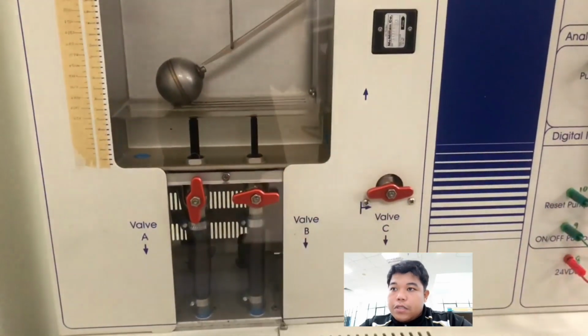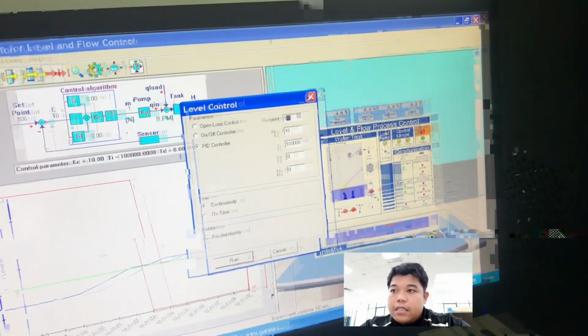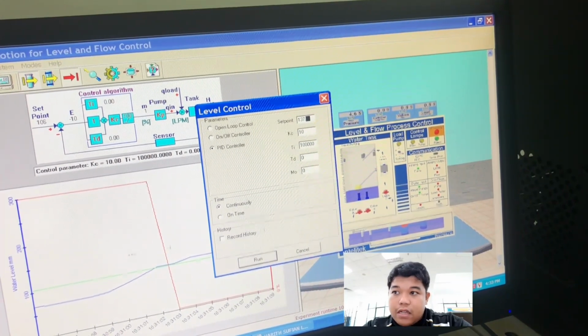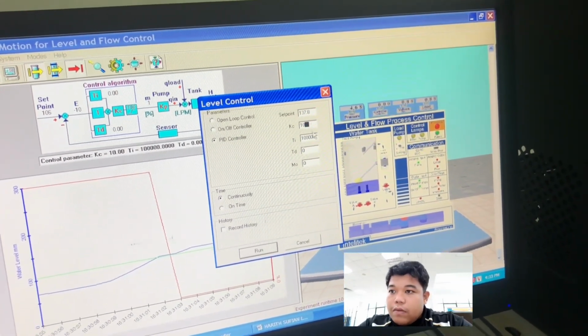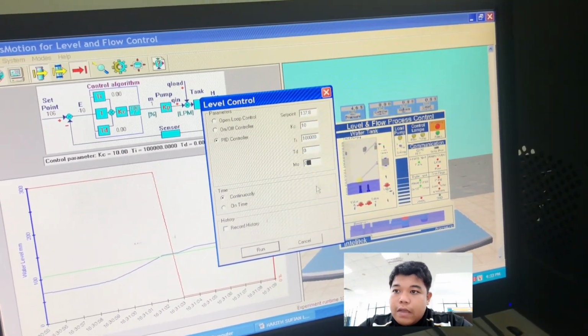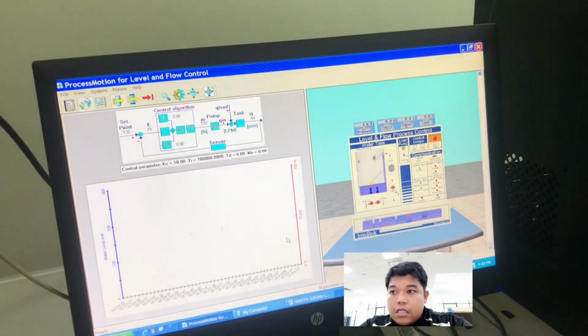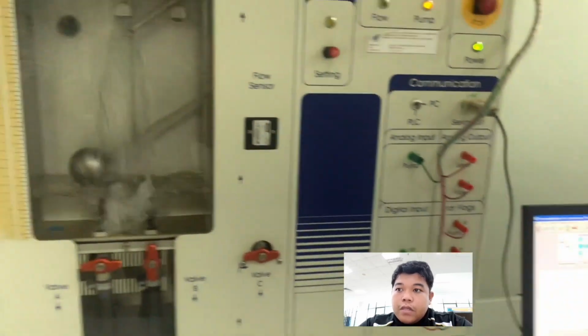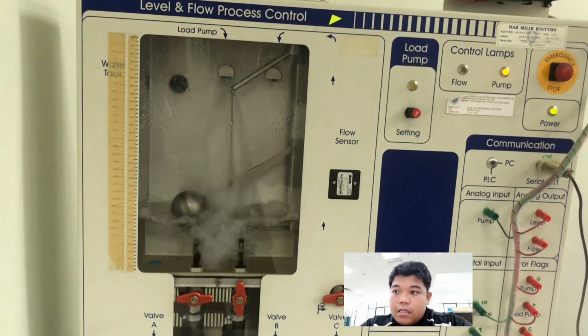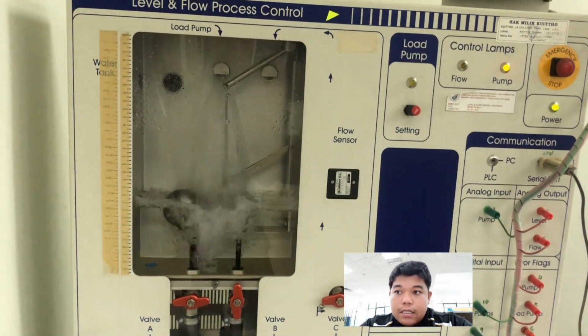Change the KC value to see the change in the system. Vary the KC setting to see how the proportional control affects the system response. First, reset the set point to the initial reference value from tasks 1 to 3. Then click run and allow the system to come to the steady state. Change the KC to a value of 100. Perform a step input by increasing the set point by 30%.